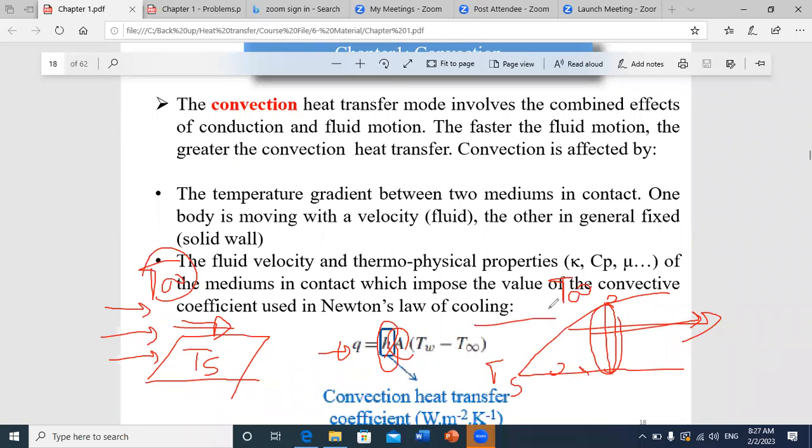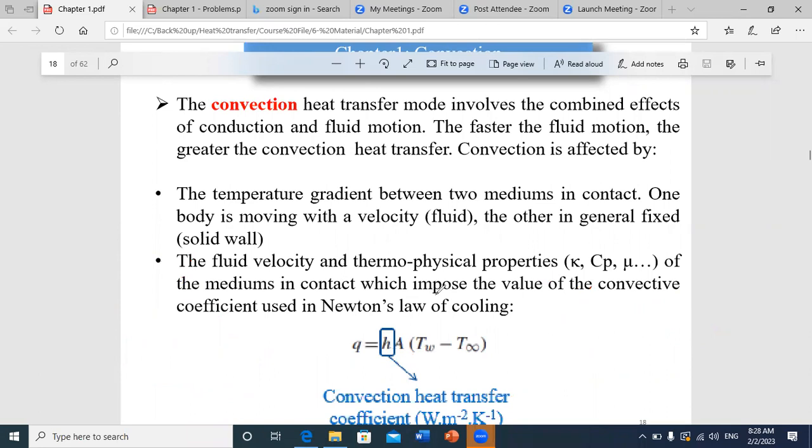If you blow water on a surface, it's not like if you blow air. If you take the example of your car, the thermal combustion taking place in your car will lead to a very high temperature of your engine. Your engine needs to be cooled. You don't rely only on cooling by air. You should cool by water, or by a refrigerant that will be characterized by a relatively high convective coefficient. So this convective coefficient is really affected by different parameters, and that's why we need to perform experiments to determine it. And then once we do these experiments, we can summarize results in tables and in charts.